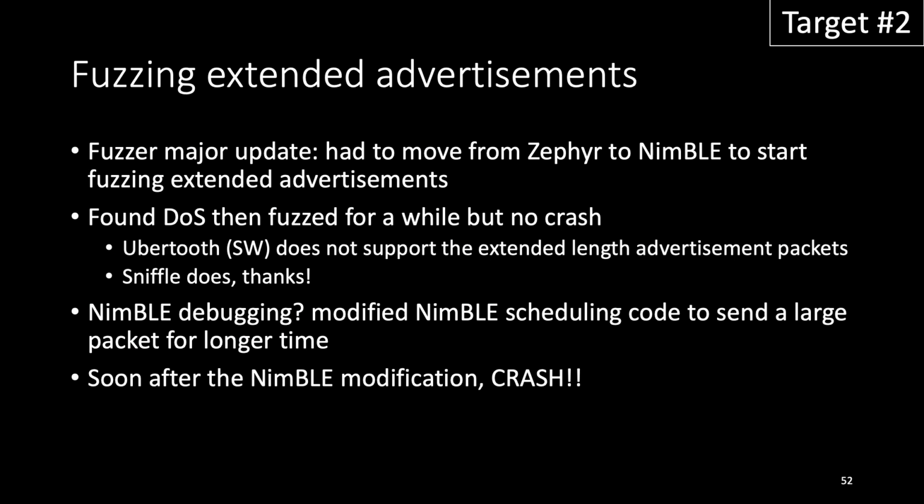And now I just started fuzzing extended advertisement packets. But I ran into a problem, because initially when I made the fuzzer, I used Zephyr. But it turns out Zephyr does not support extended advertisement yet. So I had to change my code to use NimBLE.